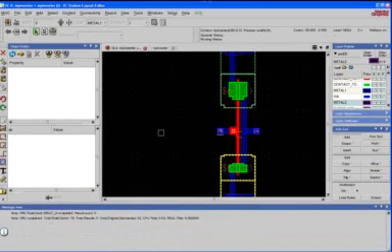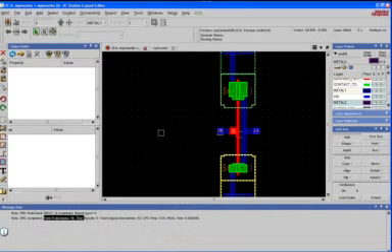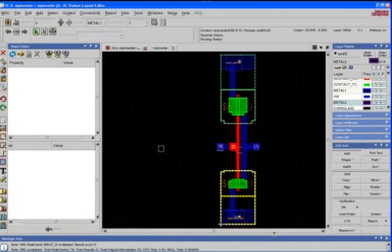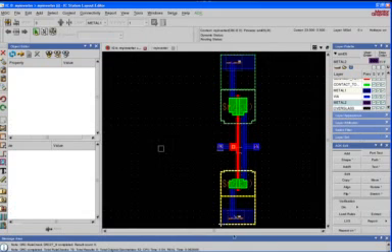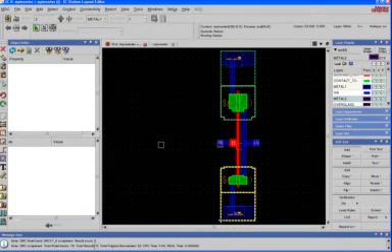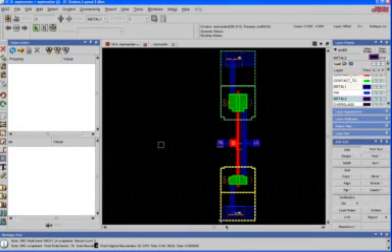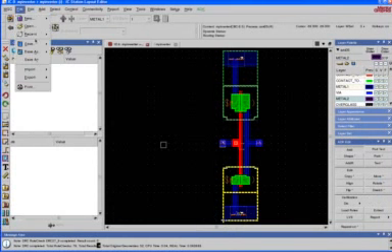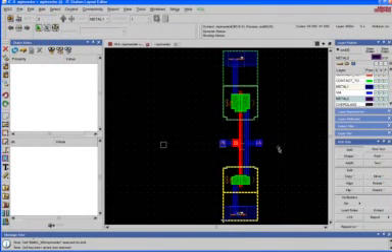If there was no error, you will see total rule check, number of rules that were checked, total results 0. Total results 0 means your design did not violate any design rules. If there was any kind of violation, you would see total results number greater than 0. In that case, you do DRC first to figure out where the first error is, next to figure out where the next error is. So save this design. This is how you do a schematic driven layout using the ICStation tool.